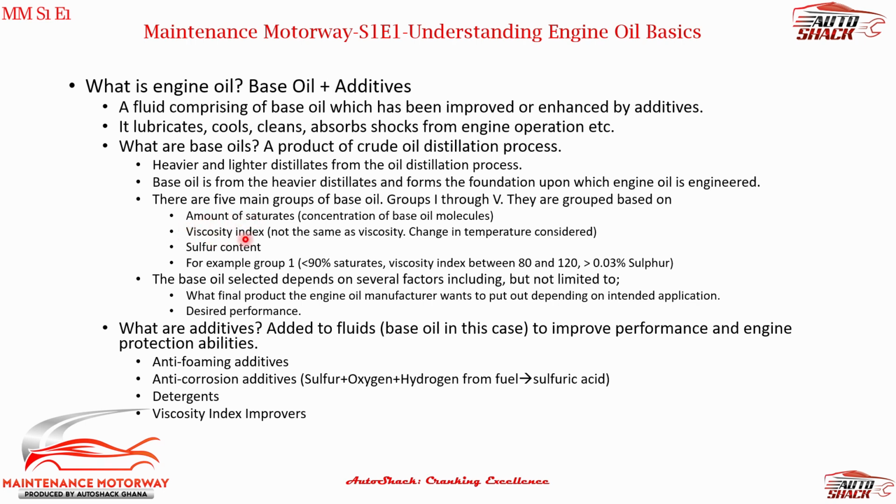Now viscosity index is another one, and this is different from viscosity. Viscosity index measures how viscosity changes from temperature to temperature, and this is very important because engine oil needs to be consistent when it's changing viscosity from one temperature to the other, because you operate vehicles at different temperatures. It's very important that it has a consistency to it when you're talking about viscosity. And that's the viscosity index.